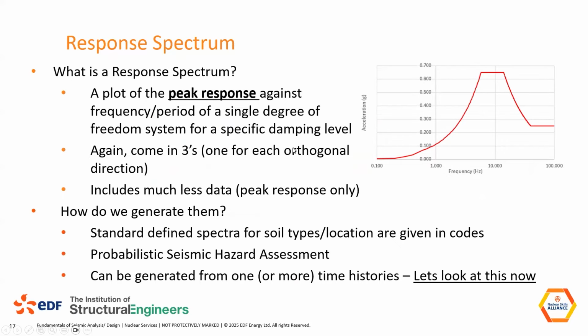it's a plot of the peak response. This is important. It's only showing the peak response. So time history, you've got the whole response. In response spectrum, you're just plotting the peak. But it's the peak response of a single degree of freedom system for a specific damping level to an input earthquake. So we still have a time history that this response spectrum is based on.